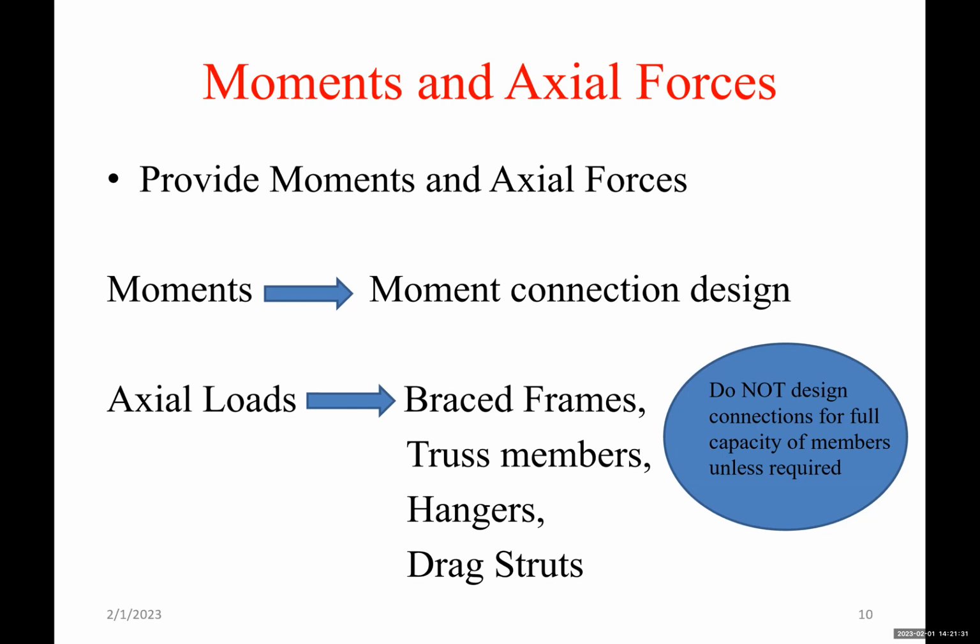So show it for the connection design, and also for drag struts in the diaphragm, in the floor framing. Show the force that needs to be designed for to transfer load from one element to another, and eventually to, say, the braced frame or to the shear wall or to the moment frame, okay?